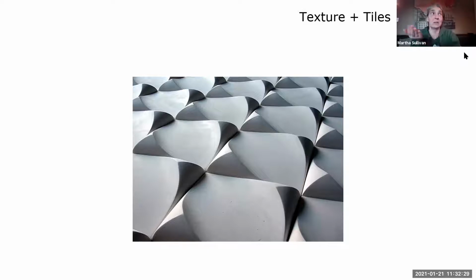That's why a lot of people would use them in a structure, because during the day they're reflecting that heat back into the environment from the sun and they slowly warm up. What happens is that keeps the inside cool. And then in the evening, that heat has been transferred into that space. So when it's colder outside, it's keeping that heat in because of that slow transfer. There's a lot of different settings for that. That was a big answer to your question. Are there any other questions?